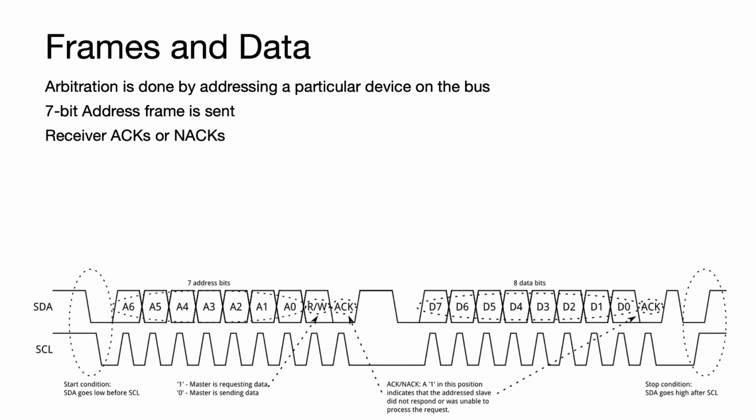Here we go. ACKs and NACKs. So with flow control, an ACK is an acknowledgement that the peripheral has indeed received the message, which is pretty cool. Because as long as you send the right address, you're going to get some confirmation on the oscilloscope or logic analyzer that this thing responded, as long as it's powered up and working.